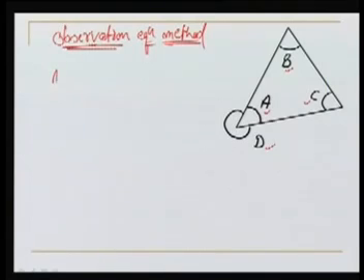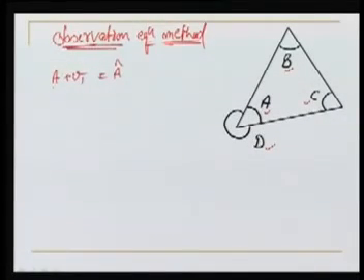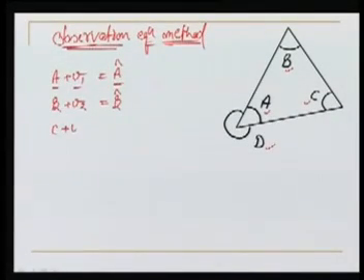Number 1, A plus V1 is A hat. In the observation equation that we are writing here, as we have seen earlier, we write equations including the observation as well as the parameter. We relate them. Here, A is the observation, V1 is the residual and A hat is the parameter. Then similarly we can write B plus V2 is B hat. Now we have only 2 parameters here, A hat and B hat, and we have to write further equations using only these 2 parameters. How can we do that? Well, we have one more observation here, that is C. In C, the residual is V3.